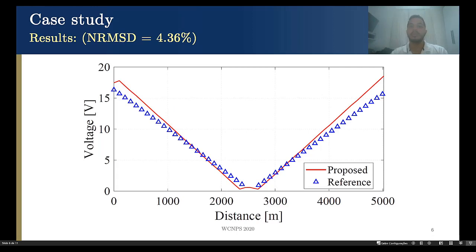These figures show the induced voltage along the pipeline, and the results obtained using the proposed methodology are compared with the results of the right-of-way software, considering the induced standards for the calculations of electromagnetic interferences.